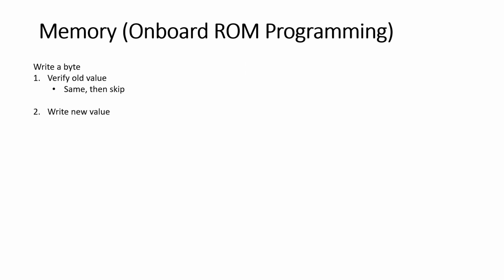If not, I write the new value like I would write that value to a RAM chip, but then I wait a few microseconds and read that value again and check whether it is different from the value that I would expect. And if so, I wait again and try to read the value again until the value matches, or if it is still different after 256 times.